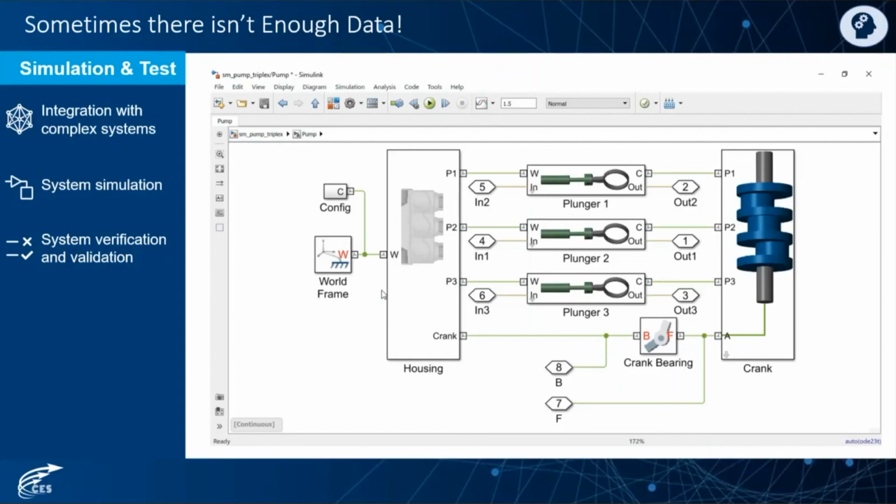visibility of how they are built internally, you can benefit from different tools that go hand in hand with Simulink to do that. For example, let's say you have a component and you don't know the mathematical equation for it. You can use things like system identification, where you give it different inputs and check the different outputs, and then use MATLAB and Simulink to derive the equation. So this is some kind of reverse engineering that happens inside the software, and it will give you an approximation of the equation of this component or this piece of hardware.